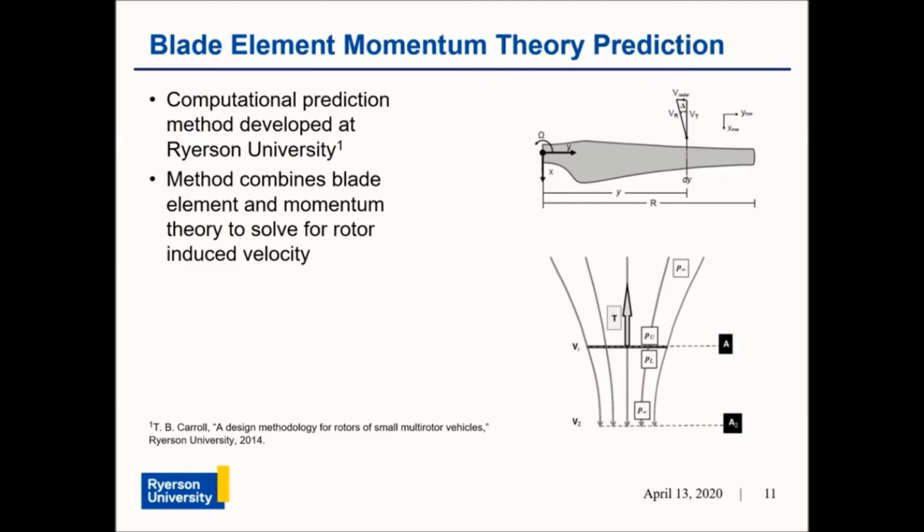Blade element theory, shown here in the upper figure, is used to determine the forces developed by the blade elements based on the inflow conditions determined using momentum theory. In the blade element theory, the rotor blade is represented using a collection of two-dimensional elements which are radially distributed.